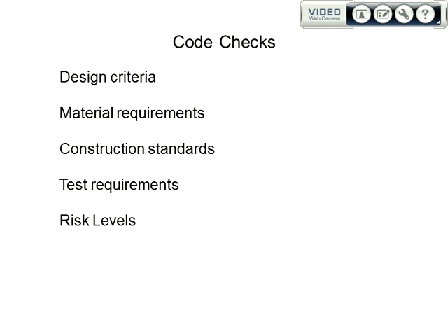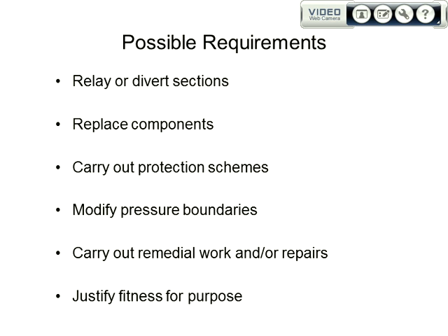Well, if TD1's more onerous than 8010, then it's already passed for 8010, hasn't it? So this is the way you've got to think about it. Now, if you hit any issues where you're wanting to change the use, and the change of use means that certain things don't comply, you've then got to think about what you may need to do to ensure that the pipeline in its new use complies with the code that you're wanting it to comply with.